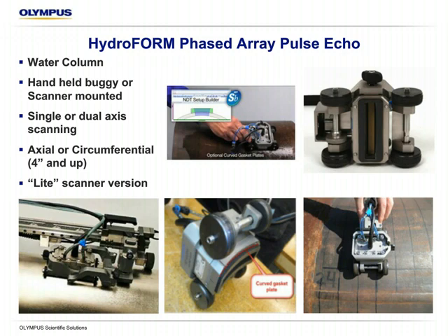No matter which, whether it's in the scanner or in this larger traditional cart, it's going to have a foam gasket that basically seals to the surface. We're going to have a water feed into this, either an automatic water couplant feed or a bug sprayer of some kind, that's going to fill this column up with water. And we're basically doing almost like immersion testing while we're scanning.